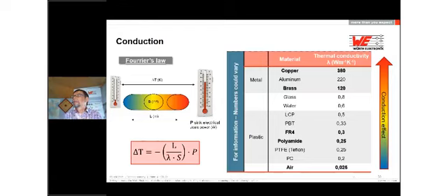So that means when we have a look at the thermal conductivity lambda, you can see the lambda here in the formula, and this lambda says the thermal conductivity. And when we have a look at it, it says copper has the best thermal conductivity of our materials in the connector. So this is also a reason why we use copper wires. Those copper wires are perfect to dissipate the heat from our connector, just to grab it from the connector and put it in the air, for example.